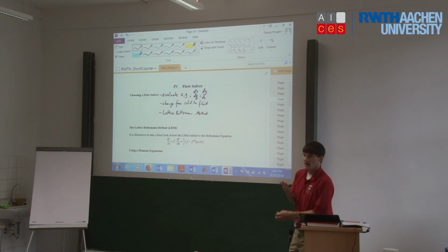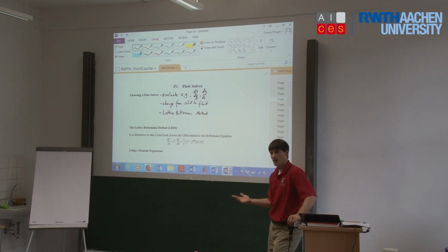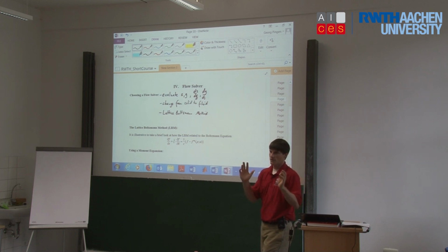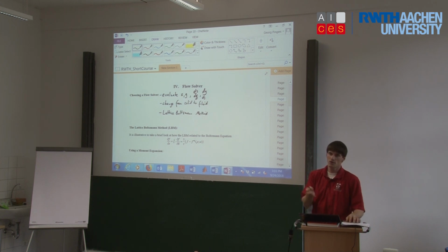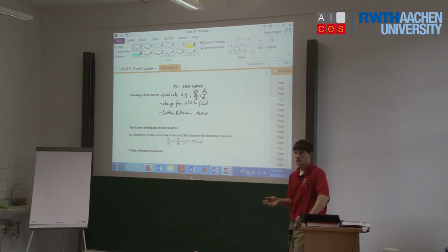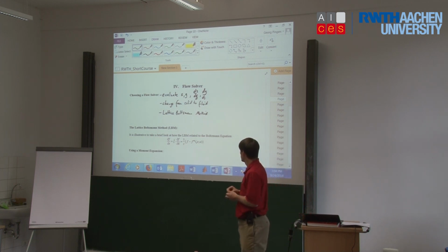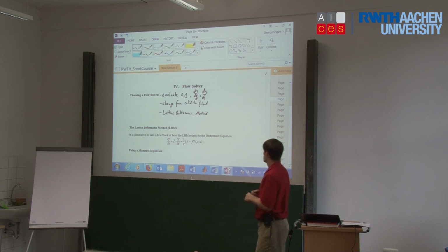And it inherently uses immersed boundary methods, which when I started my PhD program, I did not know anything about immersed boundary methods. And so I thought, well, this is super cool in the Lattice-Boltzmann method because we can do this. And then later on, the more you look around, there's immersed boundary methods for everything. So you can accomplish the same thing. And we now use Navier-Stokes-based solvers for flow topology optimization. We use some moment method-based solvers for topology optimization. And so you can do it with any solver. But in this case, the Lattice-Boltzmann method, I think, is a nice, easy implementation.